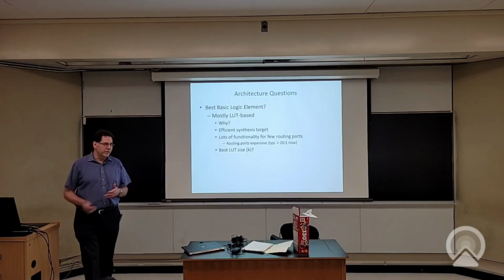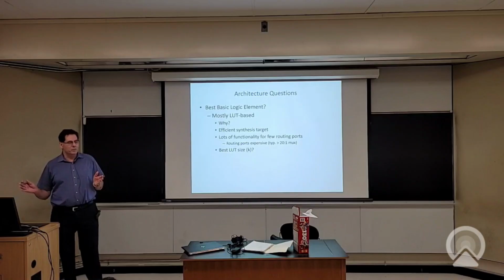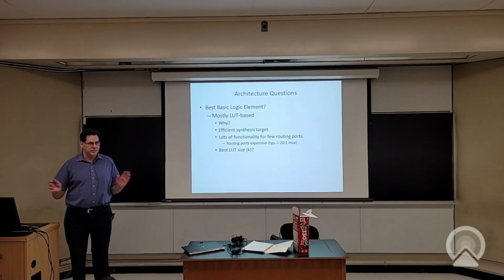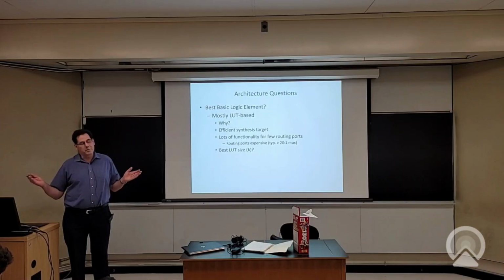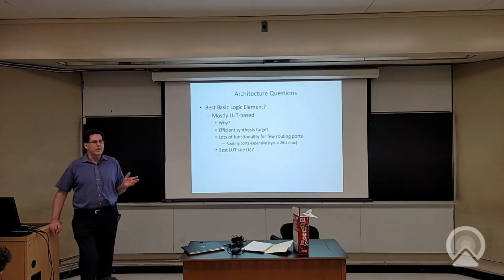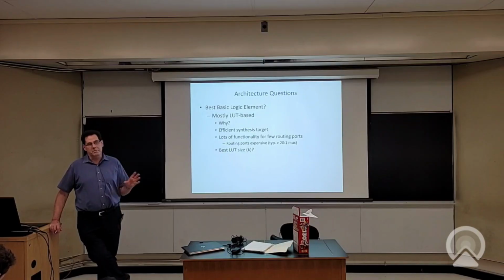And the reason is because the technology trends change. The amount of wire delay versus logic delay is changing. The SRAM area is not scaling all that well, so that's something that's now starting to happen. And maybe the biggest LUTs are a bit more expensive than they used to be because they have so much SRAM in them. So your delay and area characteristics aren't constant, and that leads people to retune things.